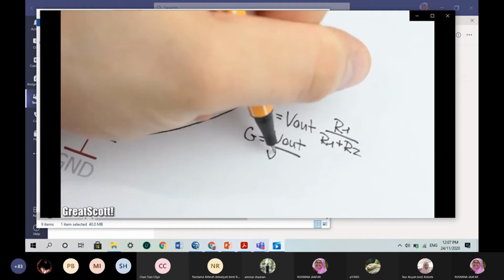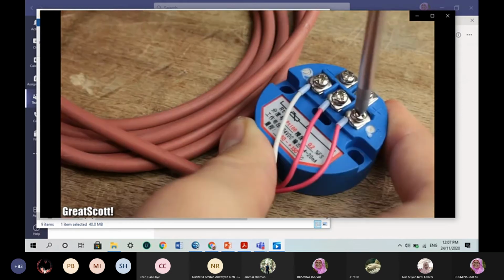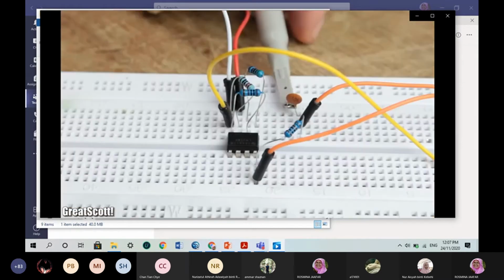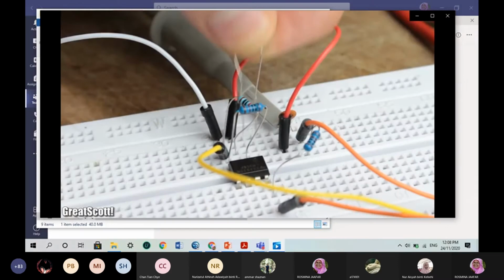Such circuits can be used to amplify the signal from a sensor, like for example a PT100 temperature sensor, or the AC signal from an electret microphone. This one creates maximum voltage peaks of around 100 millivolts AC, which I can now easily amplify with a gain of 48 by changing the 5.1 kilo ohm resistor to 47 kilo ohm.